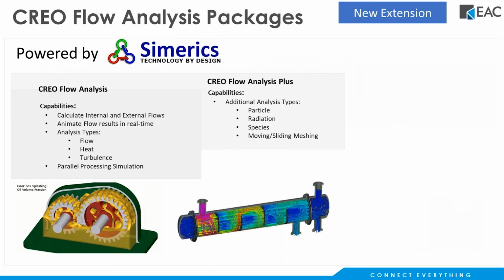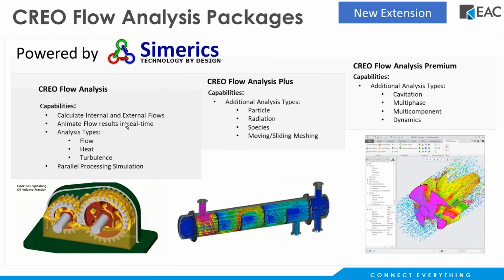Also, there's computational fluid dynamics that allows us to do CFD analysis. There are 3 different packages with that. The first one does flow, heat, turbulence, and then a little higher capability version, the plus version, allows us to do radiation, species, and a sliding mesh. And then finally, the premium end allows us to do cavitation, multi-phase, dynamics, things like that. So really, really high end. Again, it works in Creo, totally built in to the Creo interface, and it works surprisingly fast for all the stuff that it's doing.